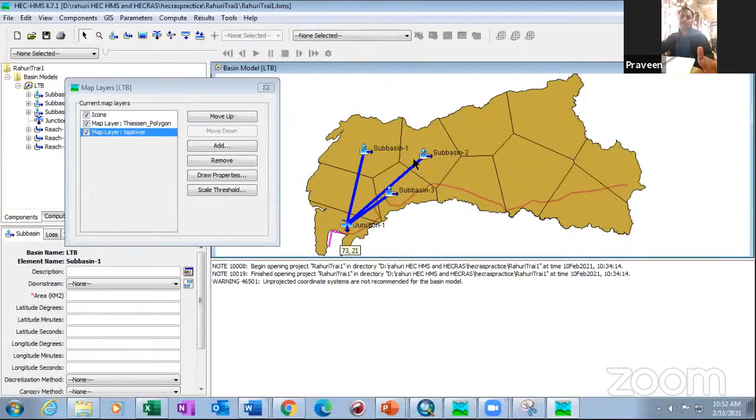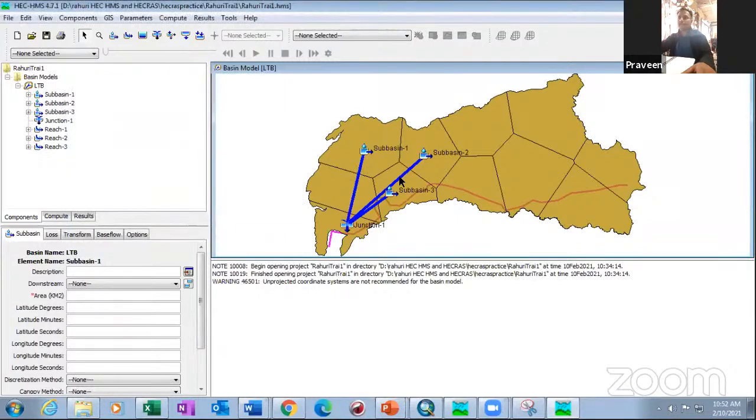If that is not added, you are like a decision maker, right? You have to decide whether these subbasins are contributing discharge at this point or not. But we can understand that using the DEM, right? So once you have the DEM, we can understand the subbasin, and then how to delete any components from the subbasin. If you have an extra added subbasin, come here, right click and say delete. When you say delete, it will just delete. And one more time, you can create and add it. You can rename it also from here. You can also move up and down, simply using the mouse click.